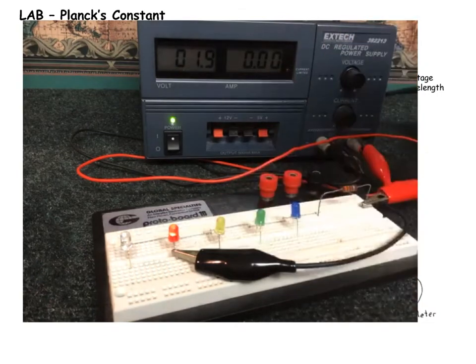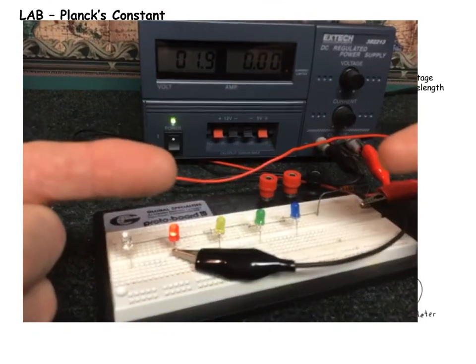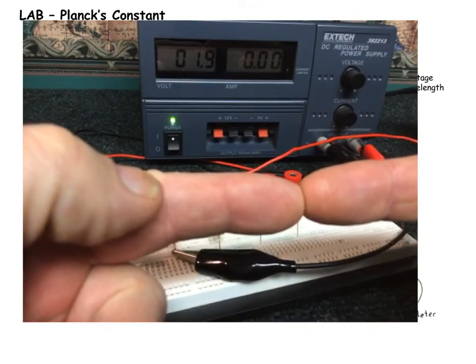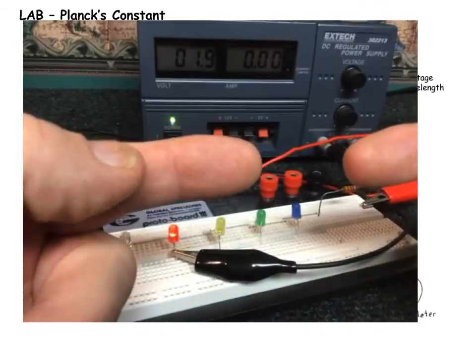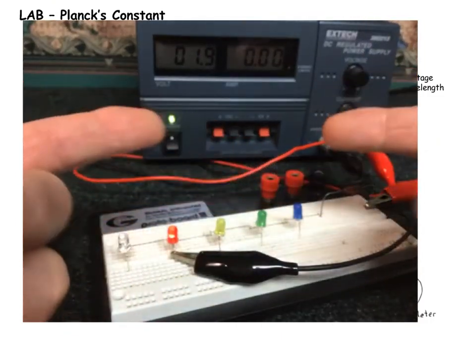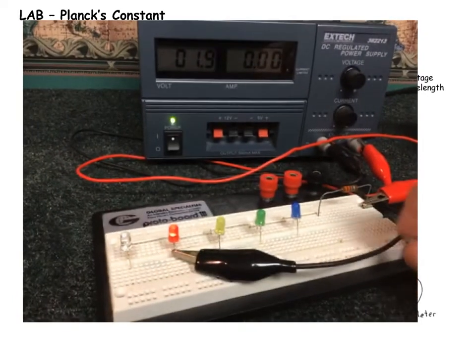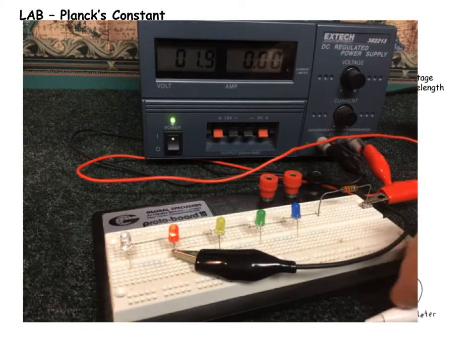Now, what happens inside of an LED is that there's two pieces of metal, and electrons have to jump from one to the other. And in order for that to happen, the electrons have to have a certain amount of voltage. And when they jump from one piece of metal to the other, they jump from a high energy level to something that's lower in energy level, and then the difference is given off in the form of light. So the energy of that photon given off is equal to that difference in the energy level, and the voltage is what's going to determine whether the electron can jump across the gap or not.